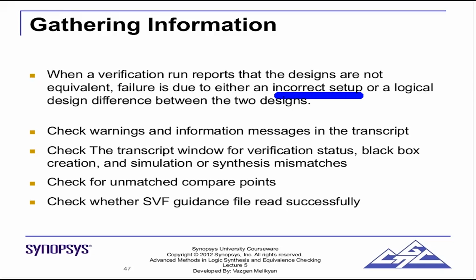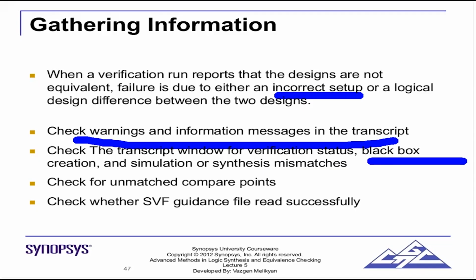You have to check warnings and information messages in the log file. This is very important before you debug the failures. Check the transcript window, that means the Tcl window in the GUI, for black boxes or for simulation or synthesis mismatch. This is very important, simulation synthesis mismatch. We have seen that in RTL coding, if you don't do good RTL coding, you can have a simulation and synthesis mismatch, and such a mismatch can also affect Formality.